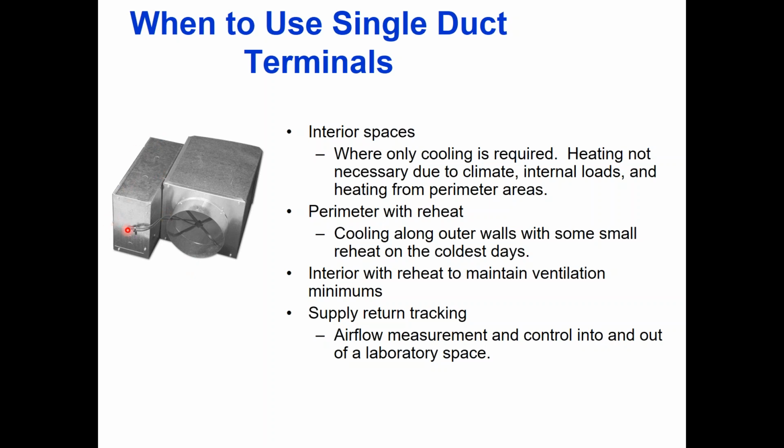On the left-hand side of this picture, you'll see a big sheet metal box. That is the control enclosure. Sometimes there is no control enclosure, and the control actuator mounts directly onto the VAV box shaft, with no enclosure around it. The times that you will need the enclosure are when you have more than just a regular VAV box. So for the traditional ones, no enclosure. You just put it on there, wire over to everything, and you're done.